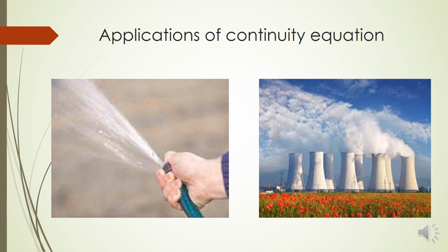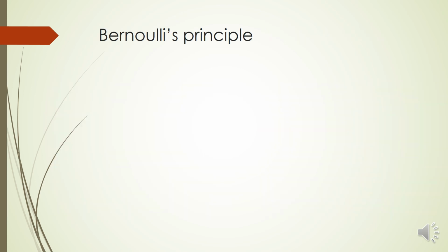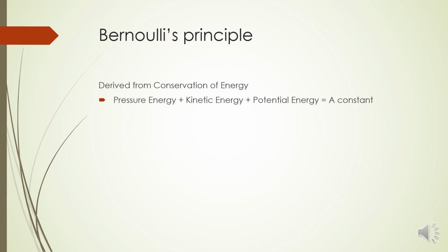Now we have one more equation that will help to understand the working of pump, that is Bernoulli's principle. So Bernoulli's principle is derived from conservation of energy. So what is this Bernoulli's principle? So we have different expressions. So one is the pressure energy plus kinetic energy plus potential energy. The total energy of a fluid flowing is a constant. So these are the three types of energy that we will come across in a fluid: pressure energy, kinetic energy, and potential energy. So these are a constant.